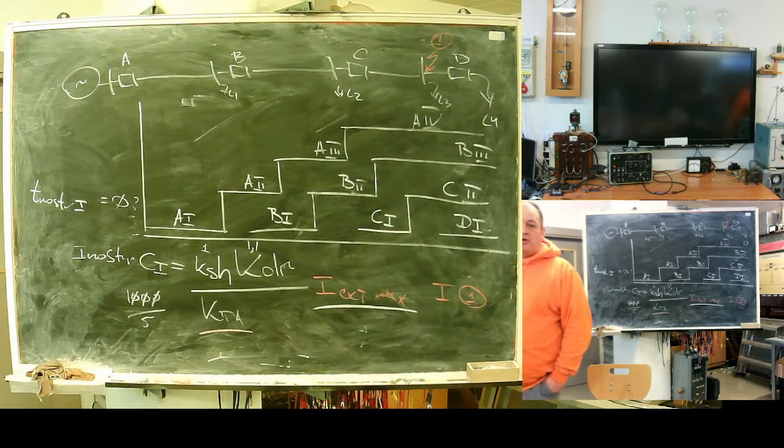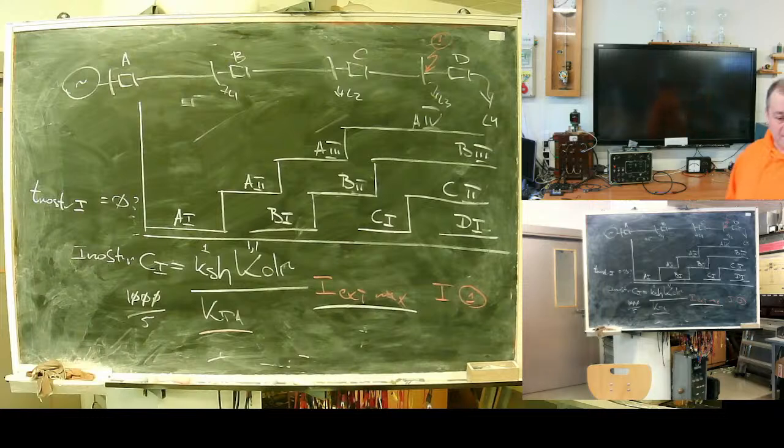Surge arresters will operate and they will create a short circuit for a small period of time. Normal surge arresters are able to disconnect current. If you set trip time shorter than the return time of your surge arresters, you will get a false trip.